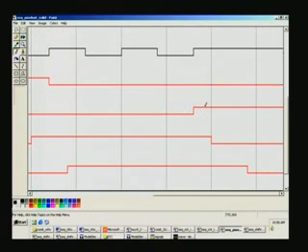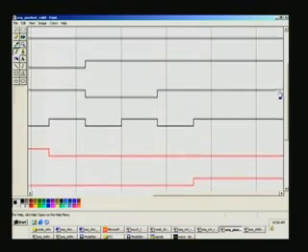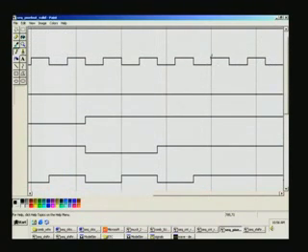So because it has gone high, what is happening here? It is going low because it has to be synchronous. It has to be synchronous with the positive edge of the clock, right? This has happened right here, but it won't take action here. Only at the positive edge of the clock can I take it. On the other hand, had you decided on negative edge transition, you could have written a negative edge instead of pos edge in that always block, right? But for the same signal, you should not put positive edge clock or negative edge clock. It is a violation, right? The tool will reject that.